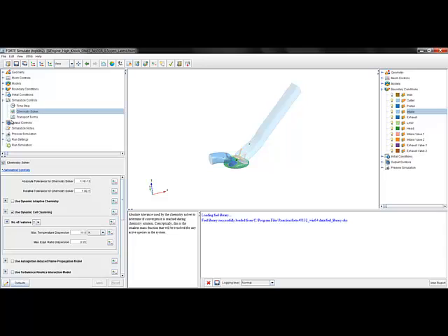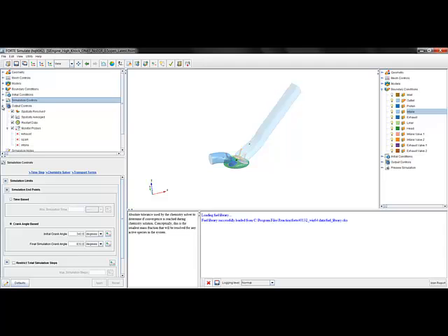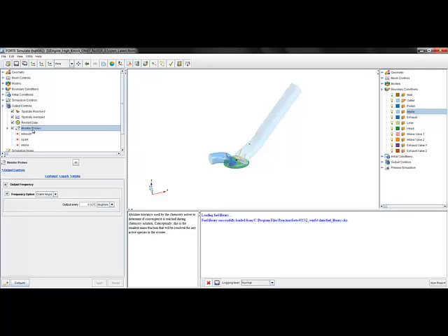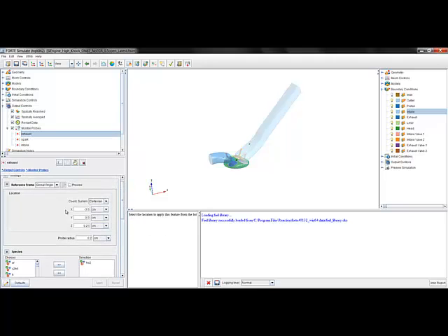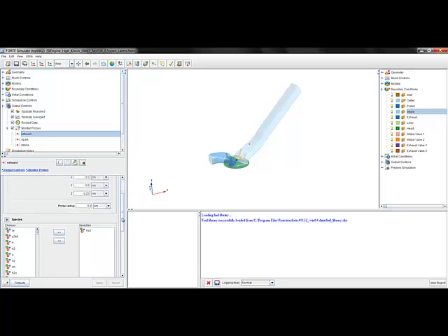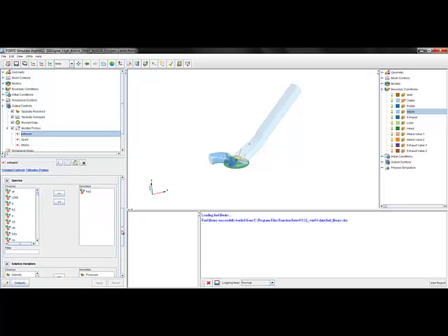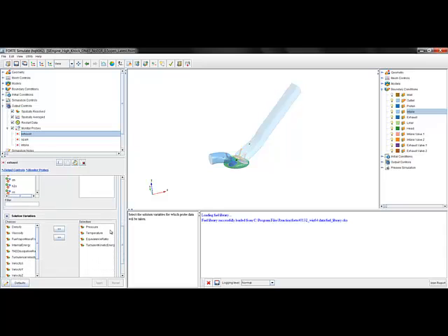But how do we assess if an engine is knocking once we have the chemistry in there? To assess knocking in an engine in Forte, Forte allows you to instrument the model with monitor probes, which are like pressure sensors in the experimental testing. This allows you to sample pressure or any other variable at a particular location in the model and to also write out any output data that you are interested in at that location. In this case, we're primarily interested in the pressure, since we want the pressure signal so we can pass it through a bandpass filter to assess the knocking in the engine.